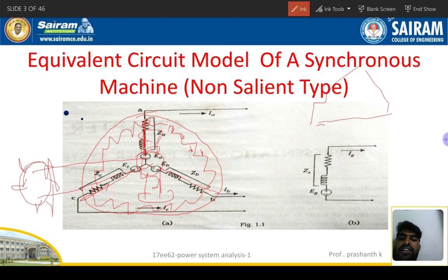This stator armature conductor cuts the rotating magnetic field, but we have to give excitation. We have to give plus minus supply for excitation of the field winding, and we are using one small DC generator coupled with the alternator or synchronous generator just for excitation. Consider an ideal power plant: water is falling like this, and the turbine starts rotating.